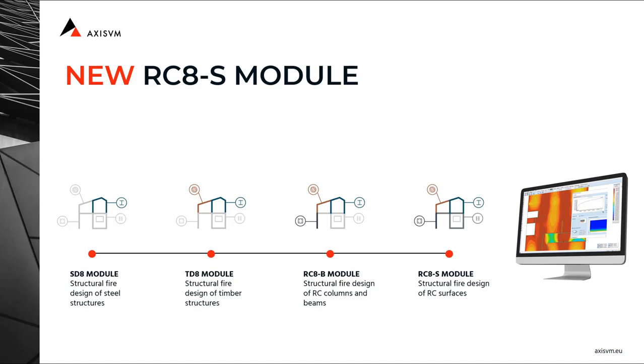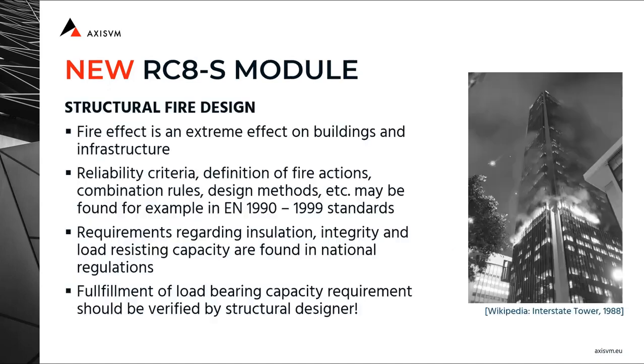which made structural fire design of concrete columns and beams possible. And with RC8S released in the current AxisVM X7 version, we are making structural fire design possible for concrete slabs and walls. With these modules, we are offering a complete solution when it comes to structural fire design for a whole variety of structures.